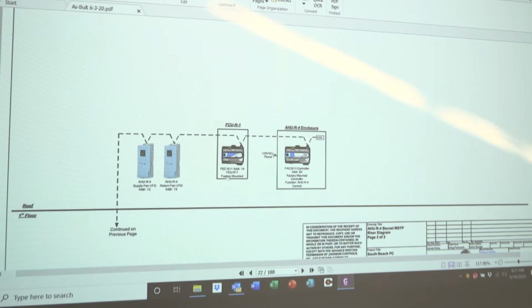There's a fan coil unit up in the storage closet that we spoke about. The air handler unit has the closet up on this floor where the isolation valves, control valves, freeze pumps, appurtenances are all in the closet. Okay, there's a fan coil unit in that closet for temperature control of that space. You have your FAC controller for the air handler.